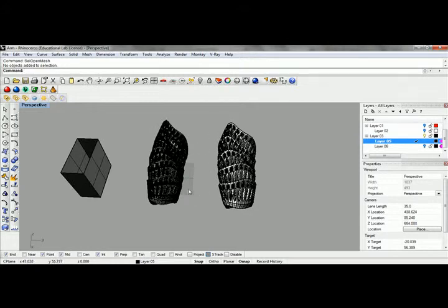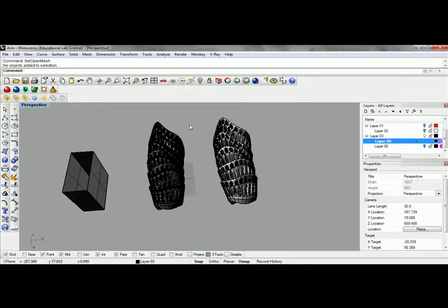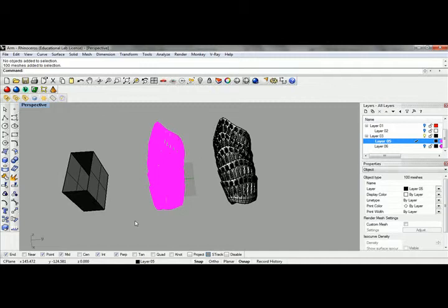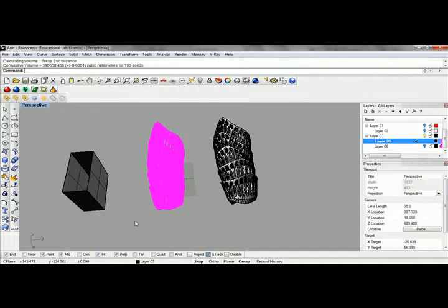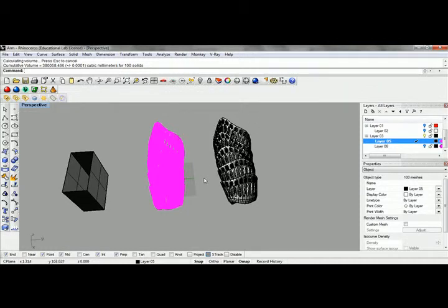So before we actually get into the exporting, we have a couple of things that I do want to cover that are also advantageous here in Rhino. If you guys are trying to figure out how much it's going to cost, you can do a volume estimate by just typing volume. This will give you the number of cubic millimeters. You can change your units, and you can put that into inches or whatever units you're trying to find out. That will give you a relatively good cost estimate for the powder printer. It's not so accurate for the ABS machines because you'll usually do a sparse interior for the larger parts, and obviously you're not going to be filling that up with a completely solid geometry.